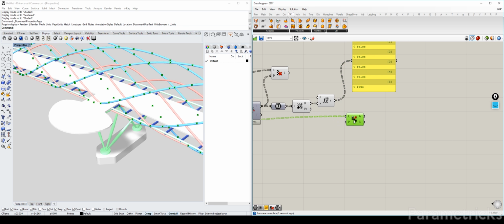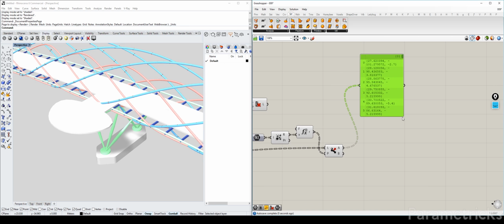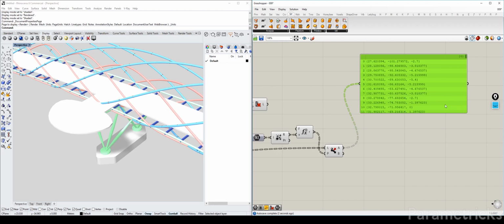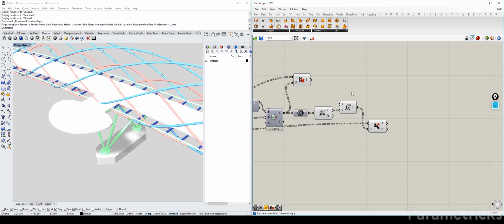So if you put that there, what you will get is, what's A? A are the ones that are intersecting. As you can see, branch 0 and 5 have items, and the other ones just go to B. And what's neat about this is that it retains our list order, or actually our tree order, something that we can re-merge back again and have that same order.